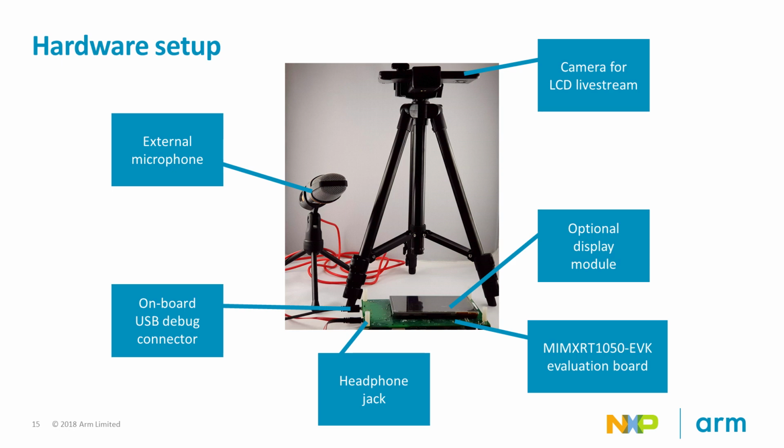It consists of a microphone connected to the i.MX RT1050 evaluation board. Although the board offers an onboard microphone, I use an external one as the LCD and the microphone are on opposite sides of the PCB. The board will be programmed and powered using the USB debug adapter on the board. The adapter is CMSIS compliant, so I can directly connect the debugger with the IDE from Keil MDK. To display the results, I attached the optional LCD module to the board, which is also available from NXP.